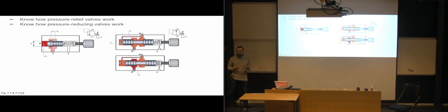And if the pressure becomes too high before it exits the valve, so if it's supposed to release pressure at 120 bars there, and it's getting 140 bars in here, then that difference in pressure means that it's going through the pilot channel over here, and it has enough pressure on this side to counteract the spring, so it's closing off the valve. And that means that it's closing off a little bit of the flow. It's basically throttling the flow there.